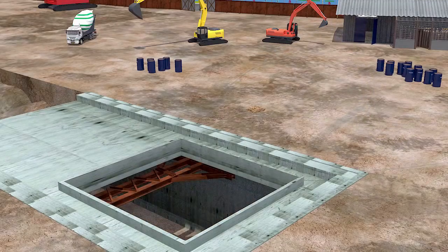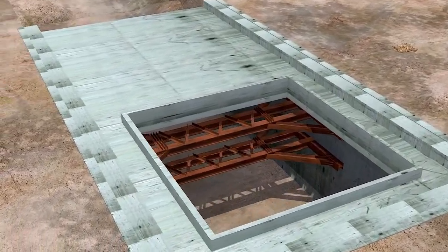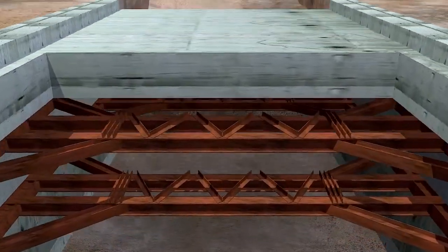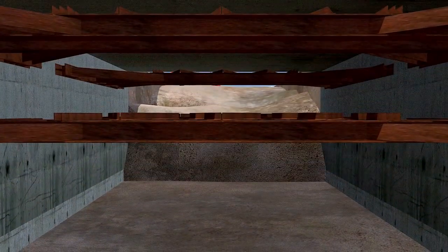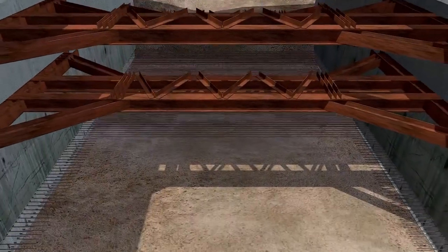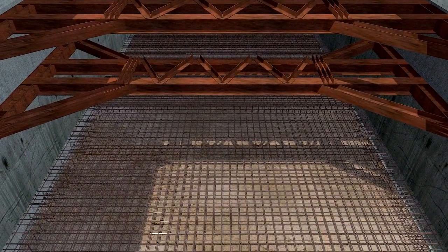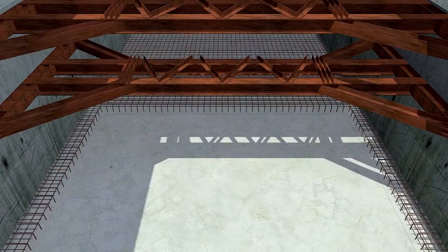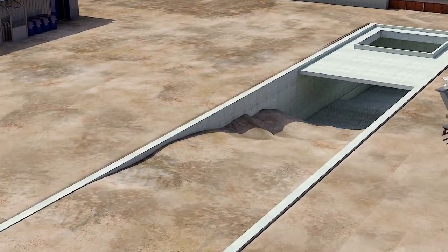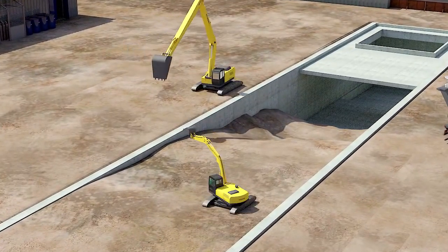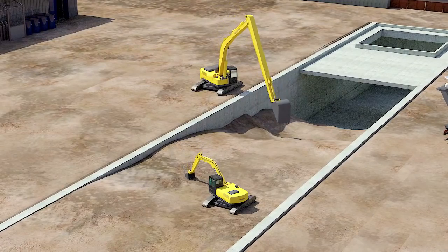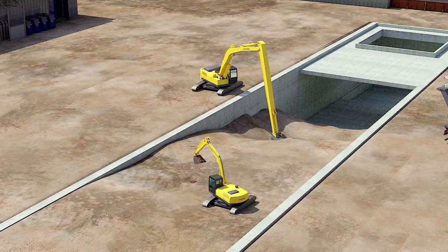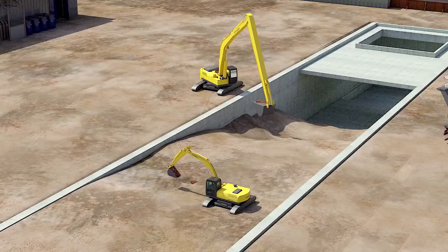As more depth is obtained, temporary structural supports are provided to counter the soil load on D-wall. The base slab is constructed similarly as per the requirement of the site. Excavation and construction of the ramp side is completed.